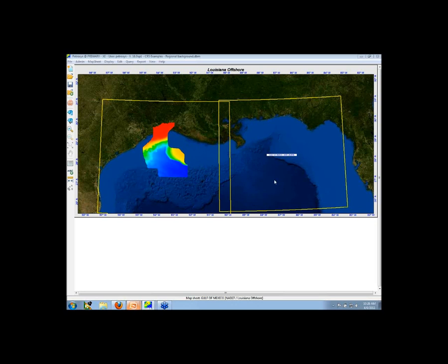And one of the really common problems, I said I'm a technical support person here. I talk to a lot of people on the phone who are having problems whenever they display data. And a lot of times down here in the Gulf of Mexico, you have different projection systems that use feet to meters, and sometimes you use the wrong one. You're using meters instead of feet. All your data shows up way up north or a little further down south because it's the incorrect projection system, so everything's showing up way, way off. So it's really important to have that correct.